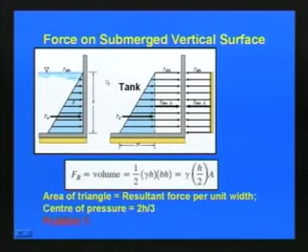Now we will discuss a vertical surface instead of an inclined plane. If you consider the vertical surface, as you can see here in this slide, this is a tank where we want to find the resultant force acting on this particular wall. Here you can see the height of the liquid, or the water, is h, and the surface of the tank is affected by the atmospheric pressure.